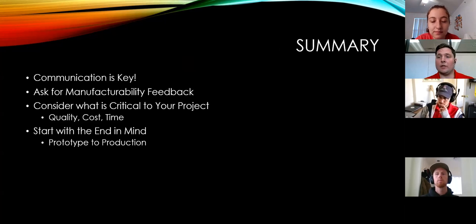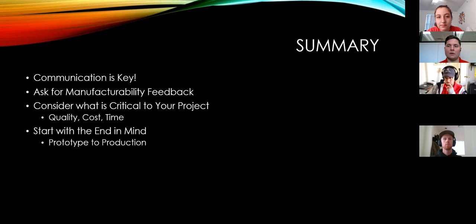So just kind of in summary of this presentation, communication is key. Talking to whoever the engineer is or whoever your rep is for your optics, letting them know up front what you need, asking for manufacturability feedback. Quite a few times I'll get these lenses that are literally unmakeable, like just physically, at least with grinding and polishing, are unmanufacturable. Sometimes they show up with a step on a convex radius, and if you think about a full aperture grinding and polishing process, you have to literally go off the edge of the optic, and so a step on a convex just isn't physically possible.